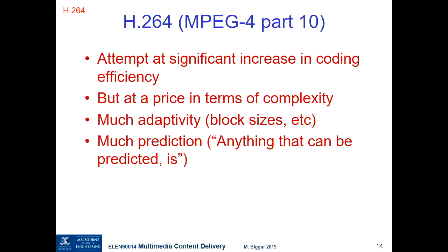And so the solution was to split up the frame into these two separate fields and sample them at different times. So if you think of a scene that is not changing very much, the best example is to think of a fixed scene. Then by scanning the odd lines, and then the even lines, and then the odd lines, and the even lines, the picture has the same resolution as if you were scanning more than one frame.